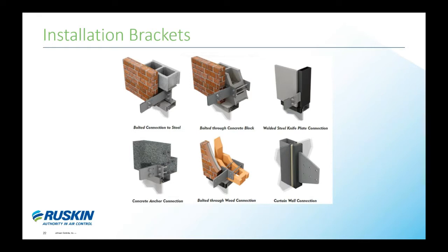Like the list shown in the previous slide, there are many ways to install, and here's a list of typical installation brackets. Thickness may vary based upon the other sunshade components. A point of note is the CMU installation due to the connection reactions. It is a common and popular construction method, but is viewed, in terms of anchoring, as poor.